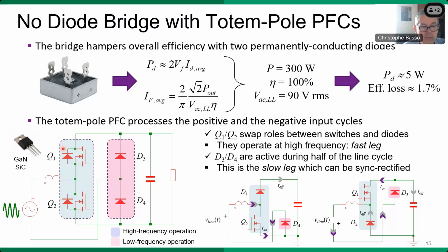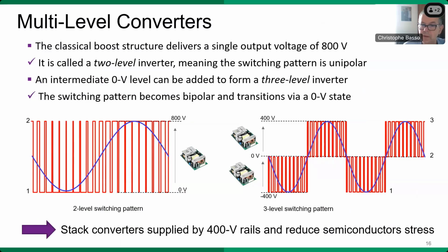These must be transistors or devices with a diode featuring very low reverse recovery losses, because otherwise you have a small short circuit on the low side transistor, and the losses at high frequencies are difficult to keep up with. So in that case, GaN transistors or SiC are well adapted for this type of operation, and you can increase the switching frequency without suffering too many losses.